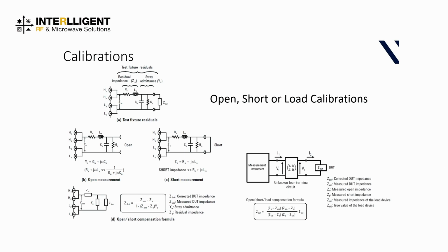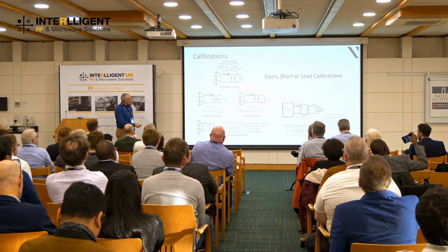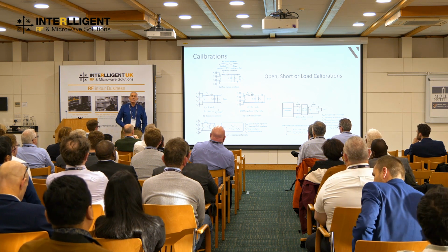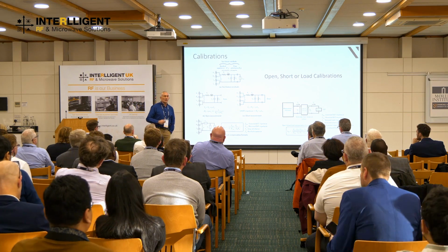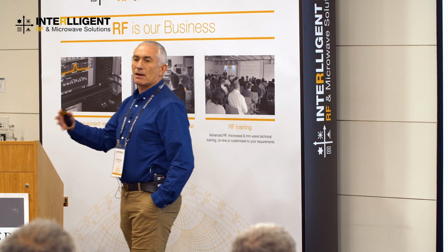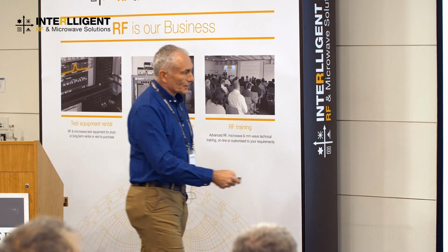I stole this from the manual of LRC meters from Keysight, beautifully explained. It shows you quite simply, that's your sample, these would be stray inductive and resistive elements inside the sample cell, and this would be your line. With a few specific measurements, you can actually calibrate those out. Basically you need to measure a short circuit, an open circuit, and a known load, and you can get whatever you want. So the techniques are very well developed, I must admit. So, easy to do.